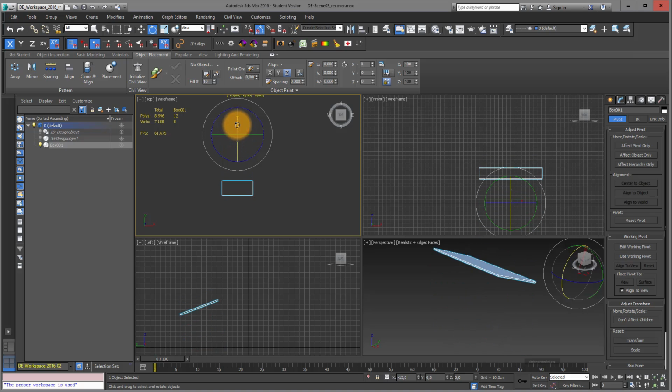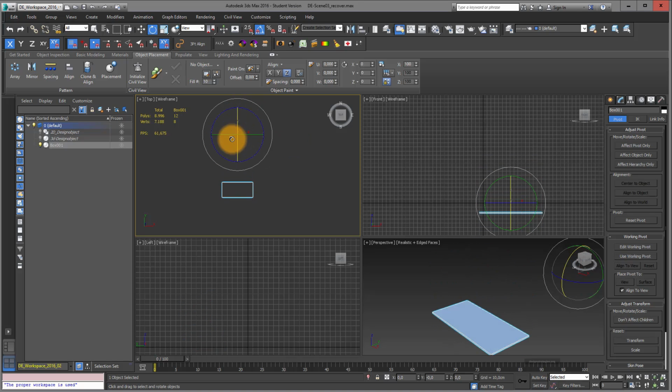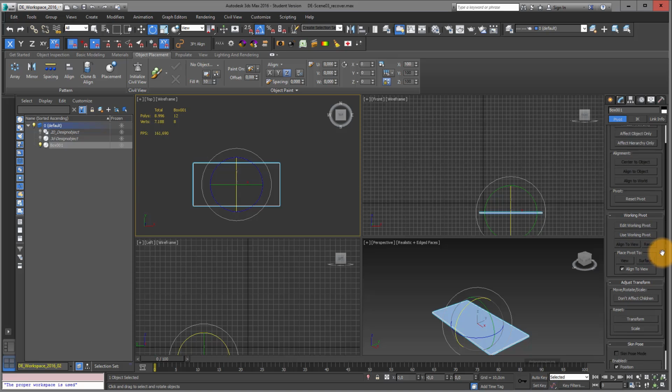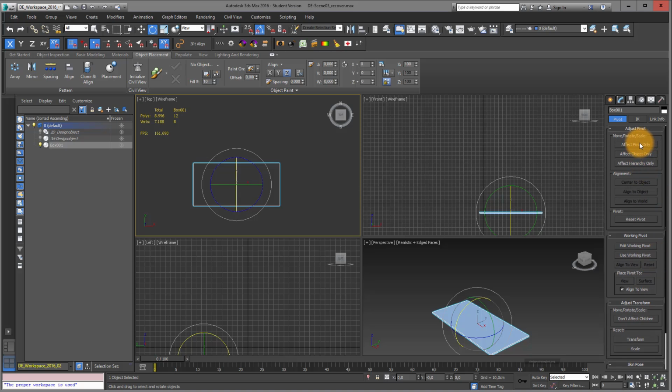Then you can see that it rotates around a point outside the object. And you can also say effect pivot point again, go to center to object, and switch it off again. And then your pivot point is again in your object. So there are many options in terms of pivot point, but these two, effect pivot point only and center to object, are used quite often.